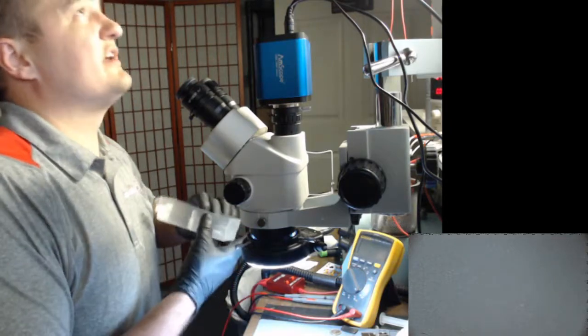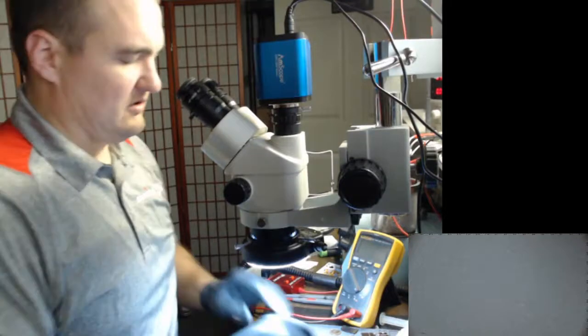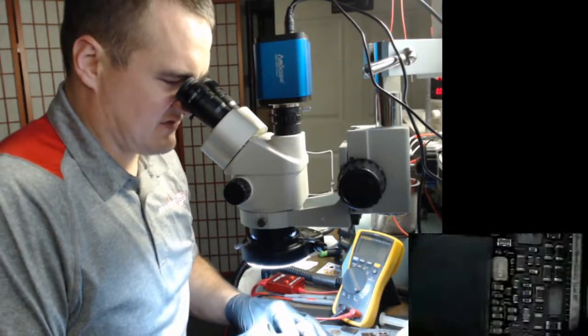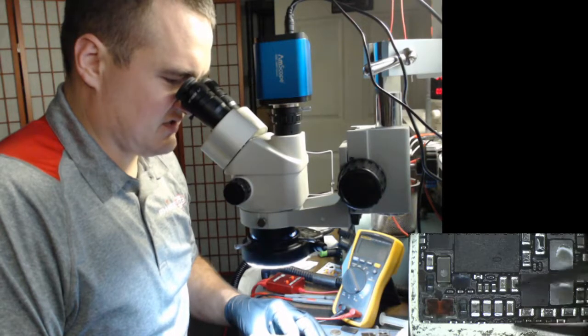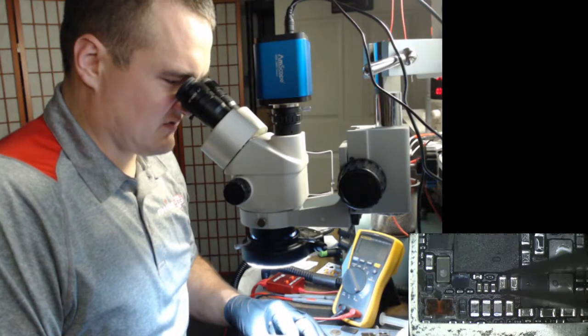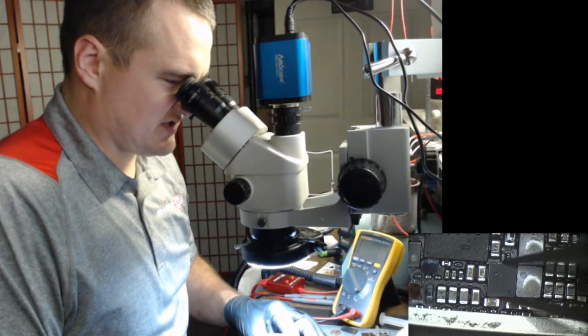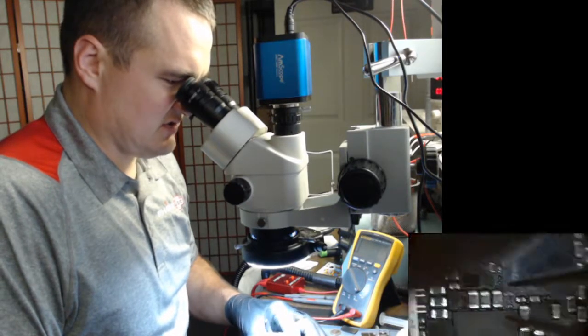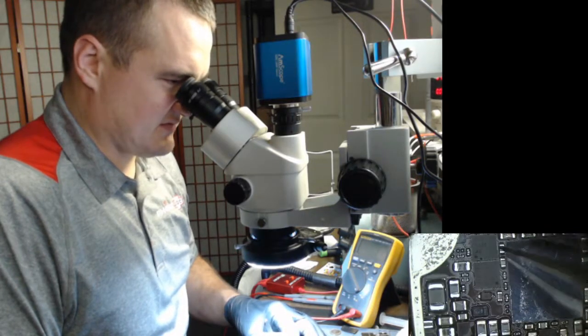So if you've got a display that's not turning on, start at the connector, look for shorted caps, look for things of that nature that would be interrupting that signal. But then you start looking around on Chestnut and see, we didn't do any of that. This was just a blind guess.